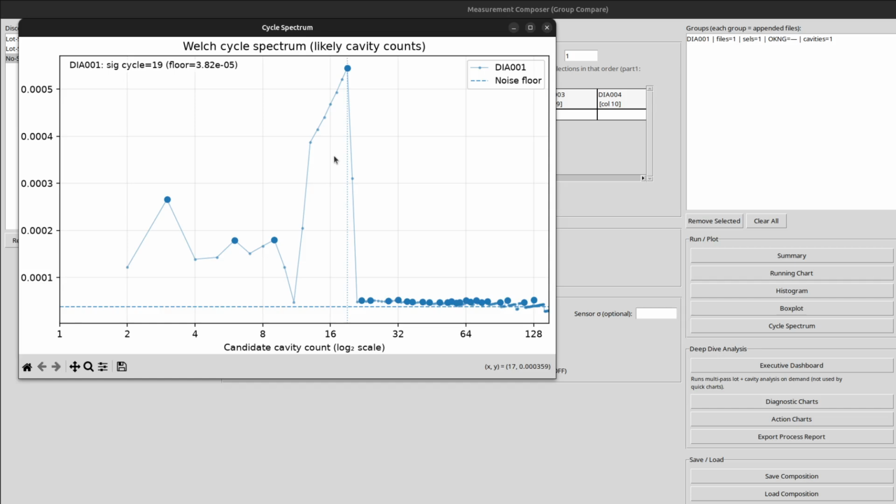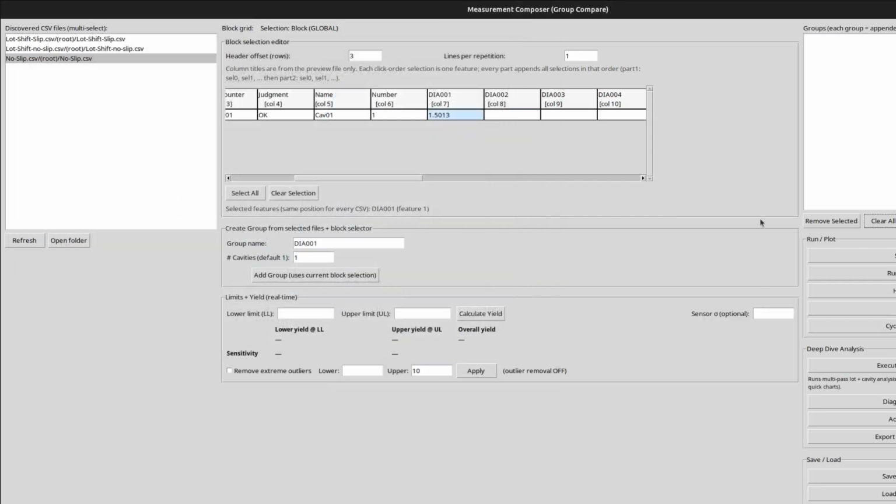In most manufacturing processes that I deal with, the processes deal in powers of 2. So we either have 2 cavities, 4 cavities, 8 cavities, 16 cavities, and that's the same for most tooling that we deal with. We don't deal with prime numbers, like wanting to have 5 parts run off of this. That just never really happens for us. So I know that this looks like a 16. It matches closest to the 16 values that we expect. So I'm going to put in that value here for the number of cavities.